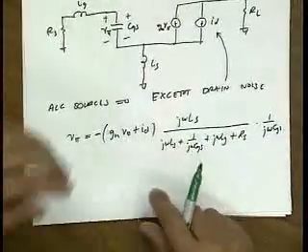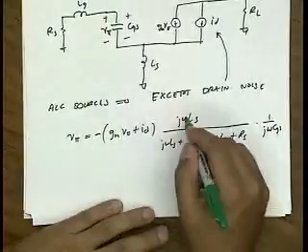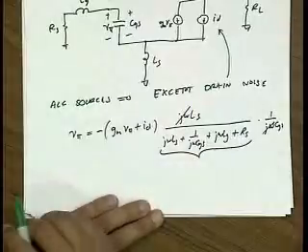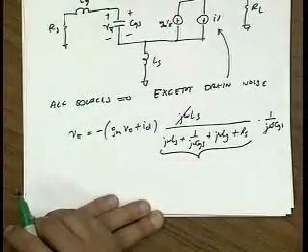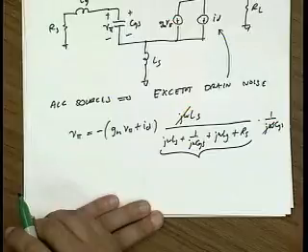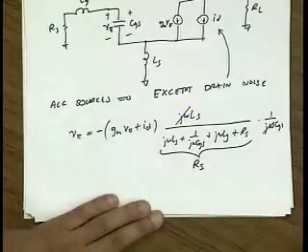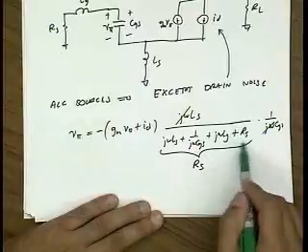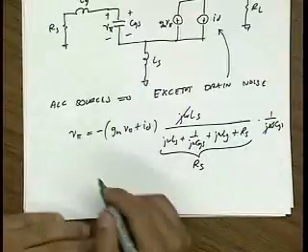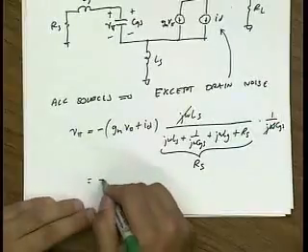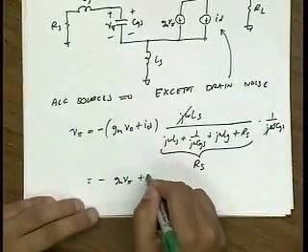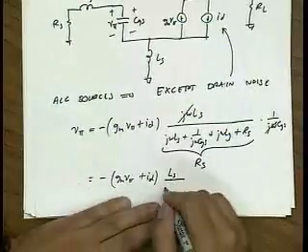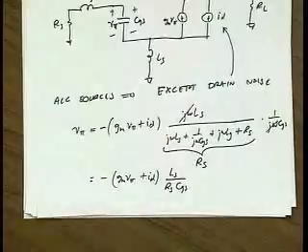Okay? Now there's some nice simplification that goes on. Well, this cancels out with this. What about here? What is this at resonance? No, it's just Rs, right? Because all these reactances just sum to 0 at resonance. And so you're just left with this term. So this, simplifying a bit, is minus Gm V pi plus I drain Ls over Rs Cgs.